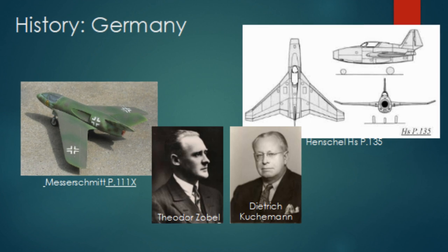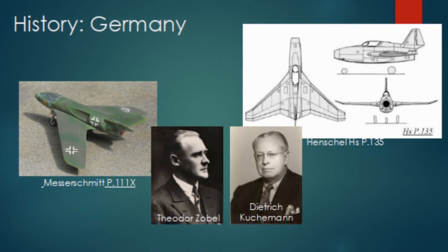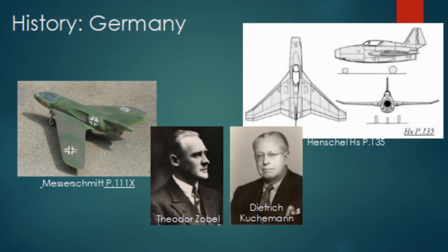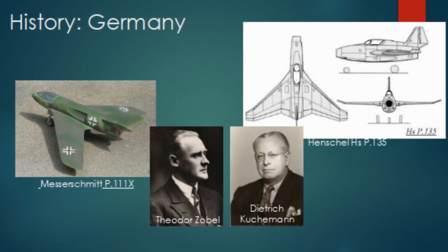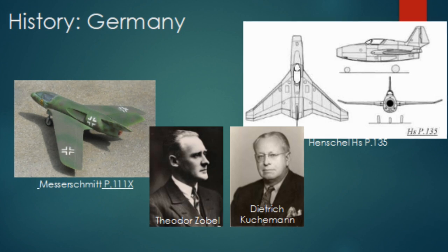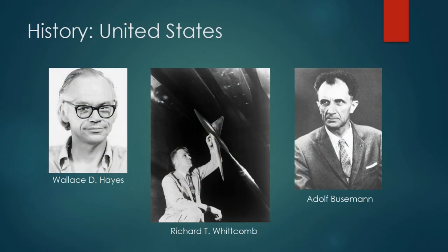Several other researchers came close to developing a similar theory, notably Dietrich Küchemann, who designed a tapered fighter that was dubbed the Küchemann Coke bottle when it was discovered by U.S. forces in 1946. In this case, Küchemann arrived at the solution by studying airflow, notably span-wise flow over a swept wing. The swept wing is already an indirect application of the area rule.